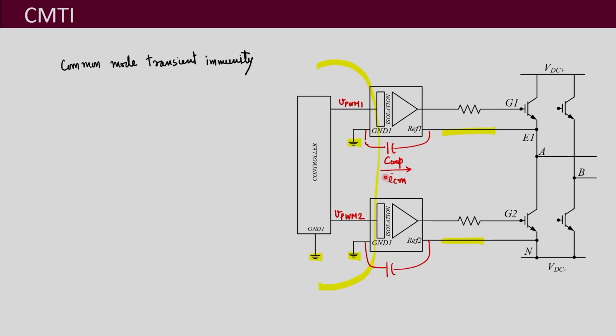So this current then comes to this, when it is going to flow in between the output and the input of this high side driver. So it enters into this circuit also. That is where it creates the interference, it is connected to the ground. So now it has entered this part of the circuit, and so it's going to be a problematic thing. And not only that, this ICM, as I told you, will also start disrupting the LED that may be there, and it is going to disrupt the functioning of this gate driver.